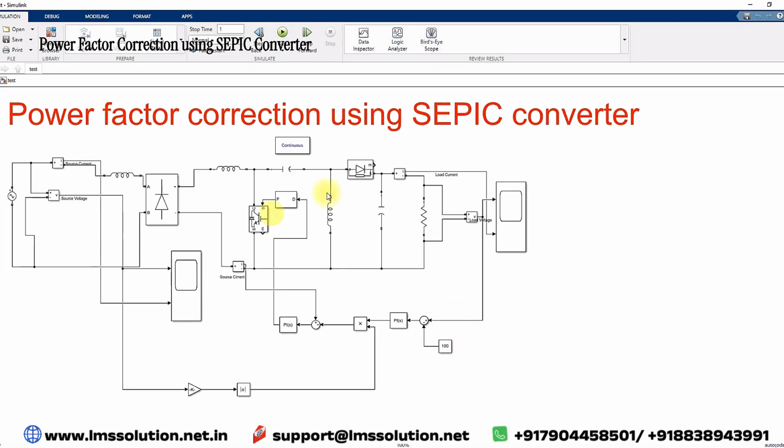In the same circuit, here we are going to use closed loop voltage and current control. We are having two loops, outer loop and inner loop. In the outer loop we are going to use the voltage controller concept. In the inner loop we are going to use the current controller concept. Here you have to measure the load voltage and compare it with the reference voltage, and when we process it via PI controller, the PI controller will generate the reference current in the form of DC. Then it needs to be converted into AC form.